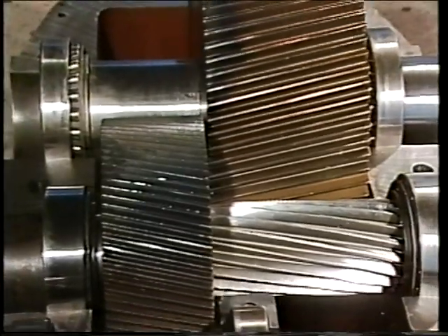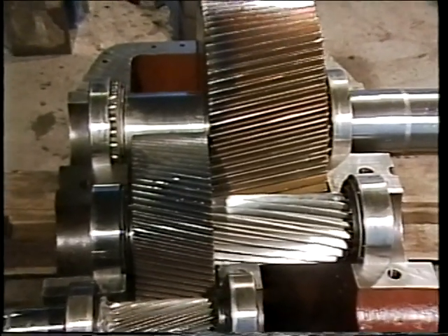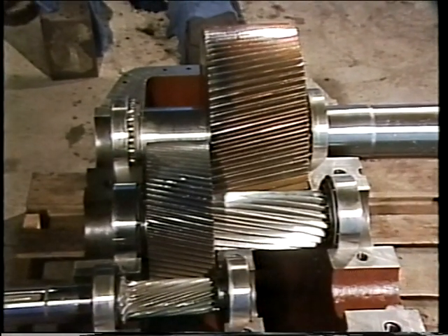A separate rotational frequency exists for each rotating part in a machine. This gearbox, for instance, has 3 shafts, and each shaft rotates at a different speed. As a result, there are 3 different rotational frequencies. When a component rotates so that its rotational frequency equals its natural frequency, the component is said to be operating at its critical speed. At this critical speed, the rotating component is most vulnerable to damage caused by problems.